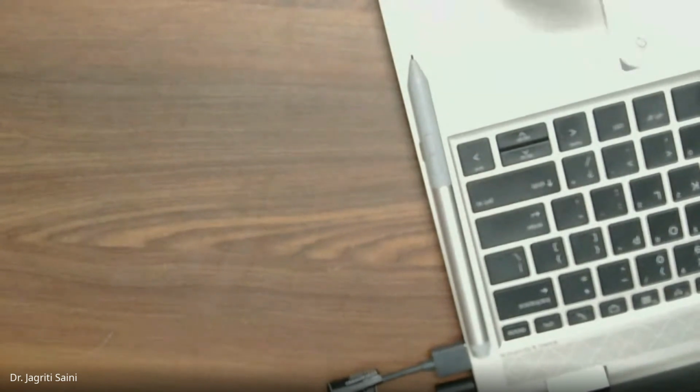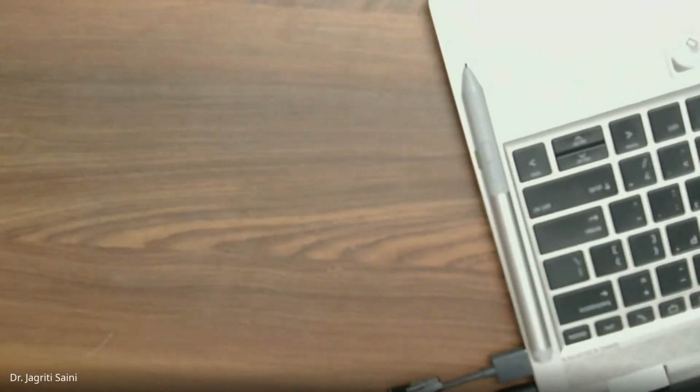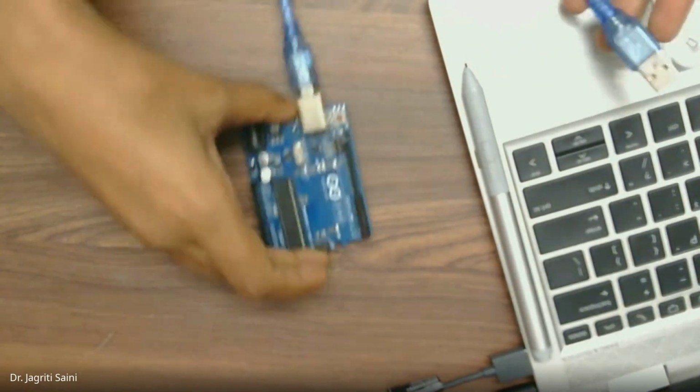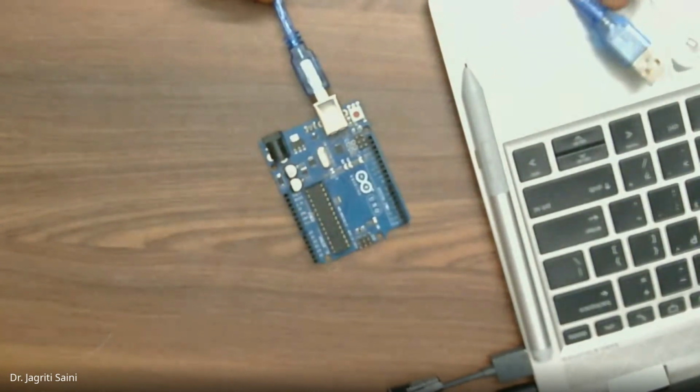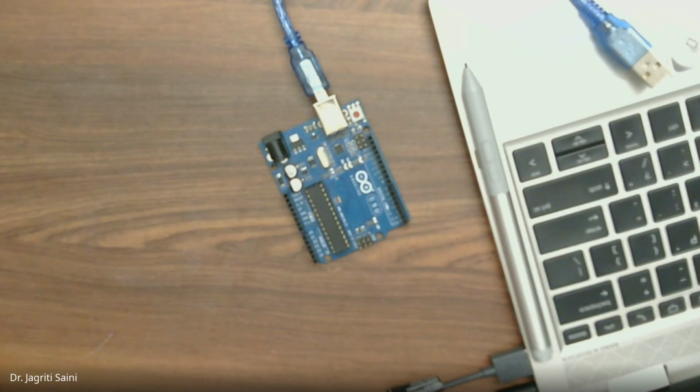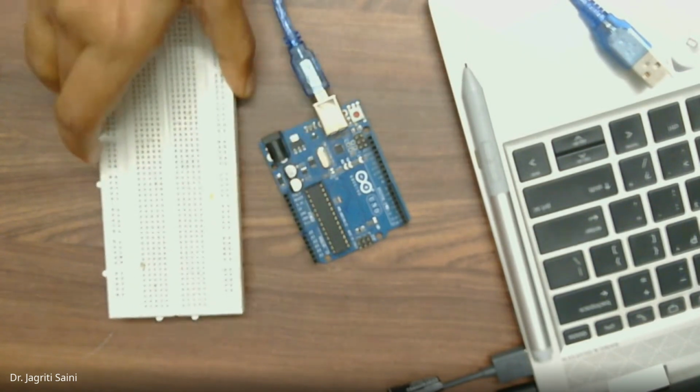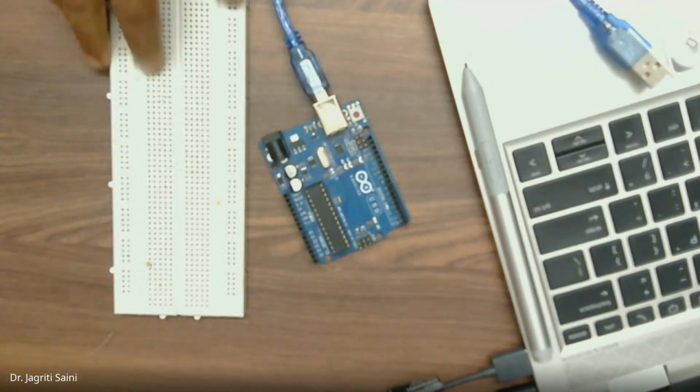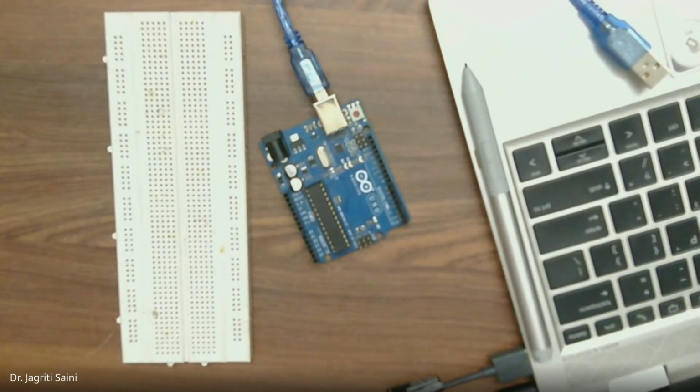Okay, so the screen is ready for all of you, and here I'll be putting up all the hardware units. The very first thing we need is the Arduino. This one we discussed yesterday also. Along with this, we need a breadboard. The reason for using a breadboard is that this time we need extensions for the hardware connection, because we need multiple 5 volt, multiple 3.3 volt, and multiple grounds. So I'll be creating those extensions on the breadboard over here.